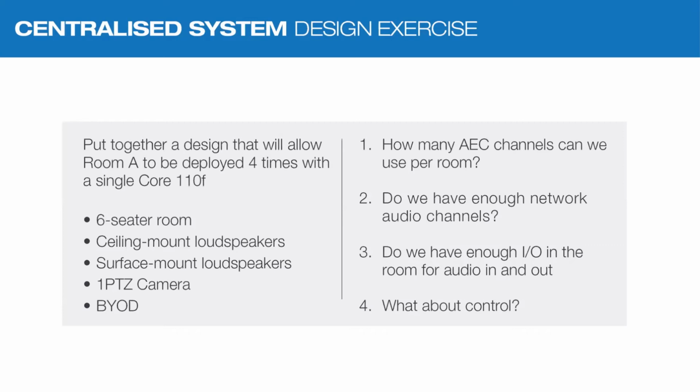Control, all we need for each room is a touch panel, 4 touch panels that go to the Q-SYS core, which is not an issue. Just take note that you'll need a UCI license in this design. And then if there's a third-party device that needs to be controlled, the scripting license needs to be added as well.